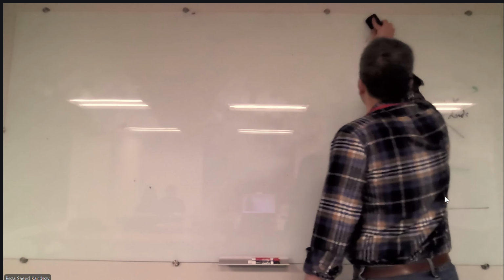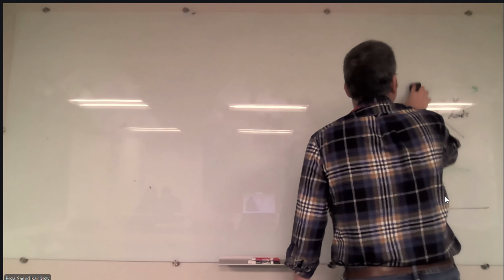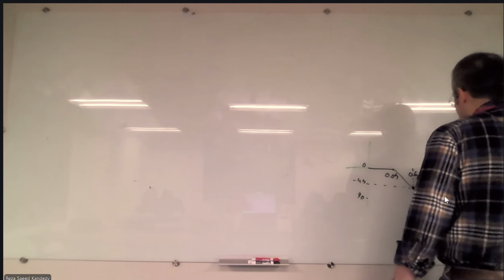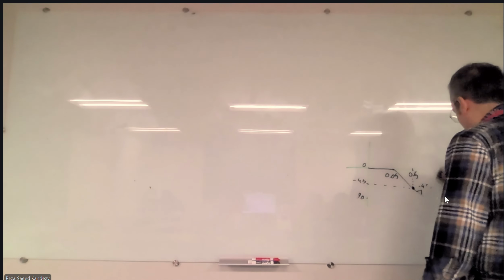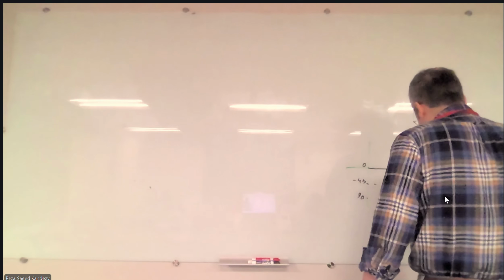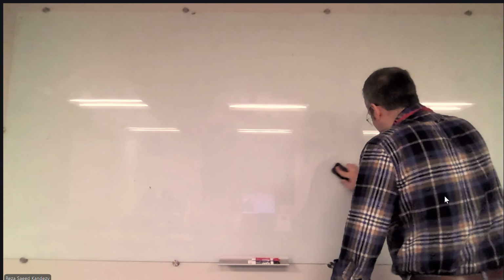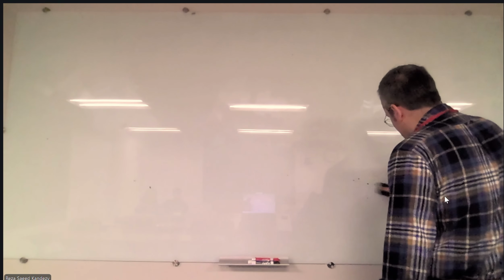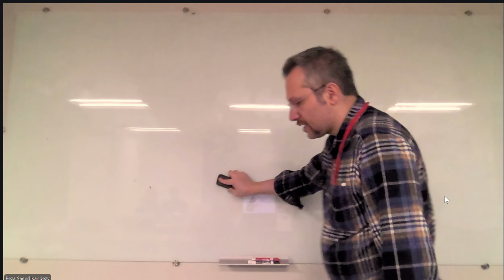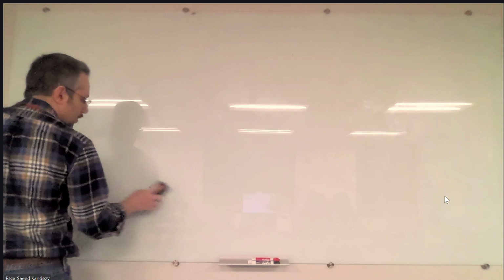So whatever transfer function we have, we can simply split it into first order and second order transfer functions, and then use the characteristics of the decibel and log, and basically the result is going to be the summation of all those individual Bode plots.